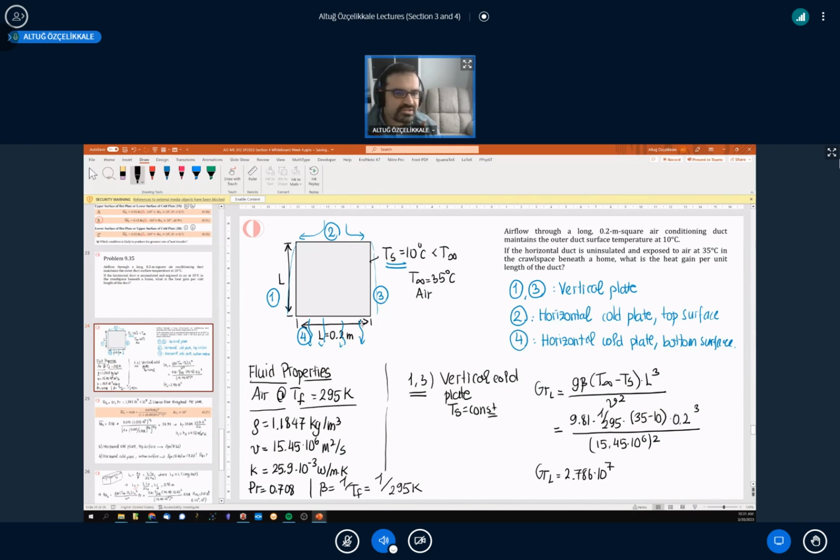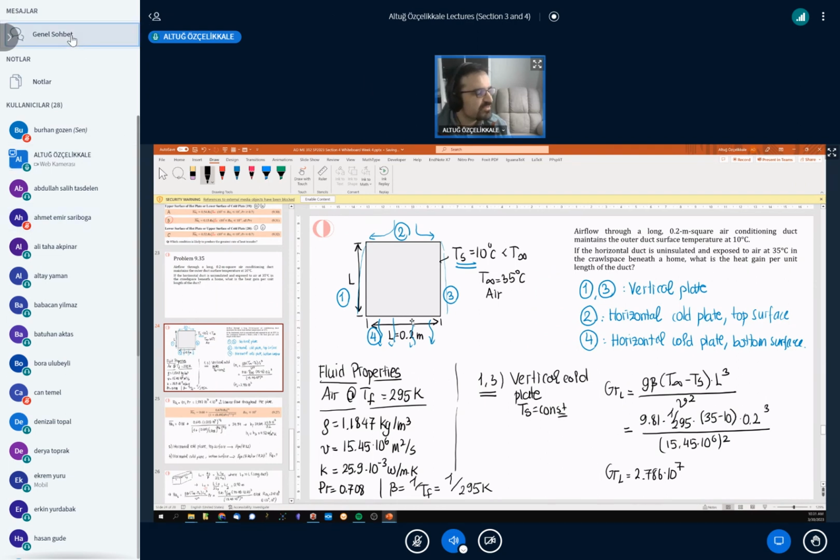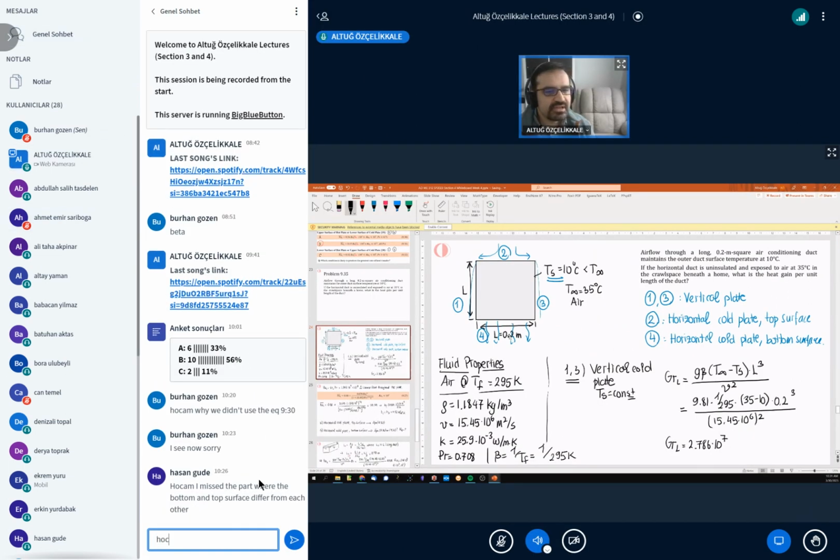Here, the boundary layer is going to be continuously interrupted at the bottom surface of the same plate, let's say. The boundary layer is going to be continuously interrupted and get refreshed by a warmer fluid from the surroundings. So we are going to have enhanced flow and some fresh fluid coming in that's going to cause a complex 3D flow with enhanced heat transfer. And as a result, we have different correlations for them.